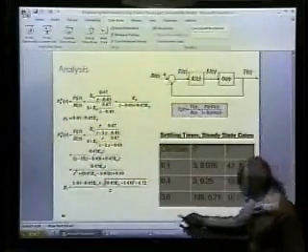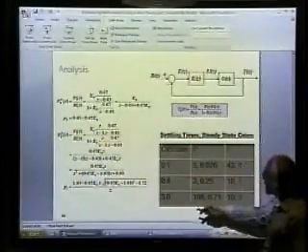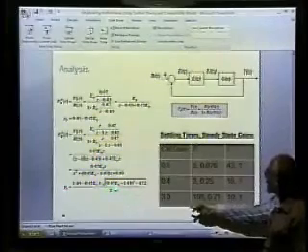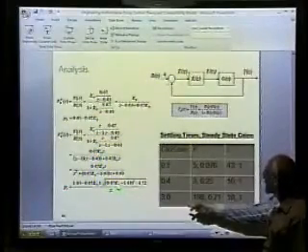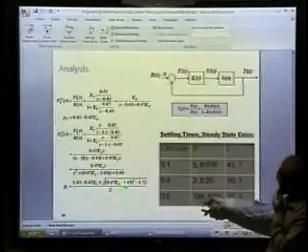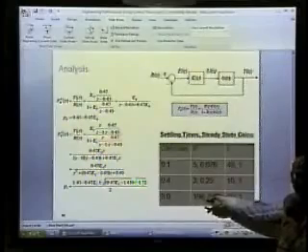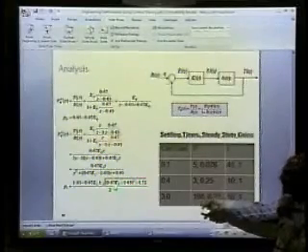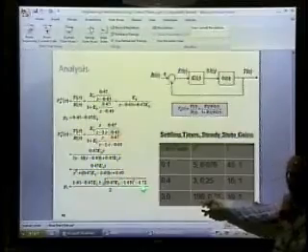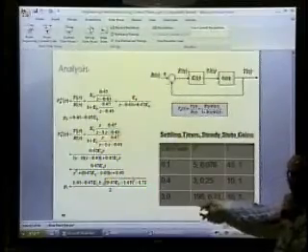I'm not going to, I mean, you can look at the math later at your leisure. One thing that's sort of interesting about this is you see what the Ki is over here. If Ki is small enough, you can actually end up with imaginary poles. Because this expression here will be smaller than 1.72, and so you get the square root of a negative number, which is imaginary. So you can actually end up with oscillations there as well.